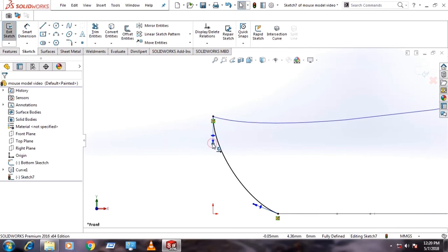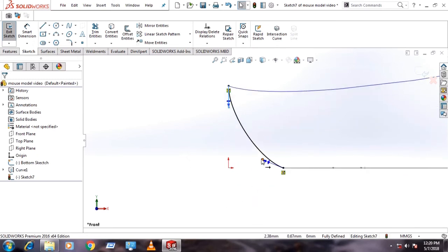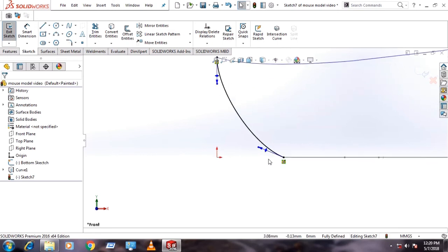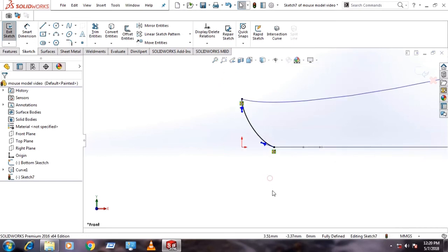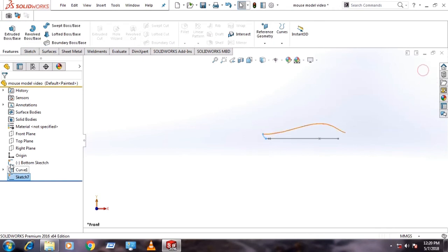Use the diagonal shape in the spline handle to adjust the direction. The arrowhead of the spline handle is used to adjust the magnitude, and the end point in the spline handle is used to adjust both the magnitude and direction. Exit the sketch.